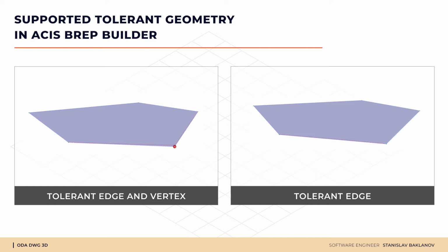from such data. But more and more users try to use non-exact geometry. For example, there is a plane, but one of the edges is not on this plane. There is a distance from the edge to the co-edge on the plane. Other examples are loops. Loop is defined by edge geometry and should be closed and continuous. End position of current curve should be equal to the start position of the next curve with some tolerance. But sometimes loops have small gaps between edges and it leads to errors during data validation.